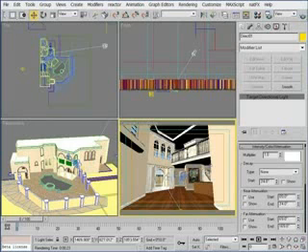And this is really an important point to understand. You really want to add the artificial lighting after you get the natural lighting from the exterior sunlight correct. And if you wait until this point when the natural light is correct, you can know that when you add the artificial lights, the changes that you see are realistic or not.